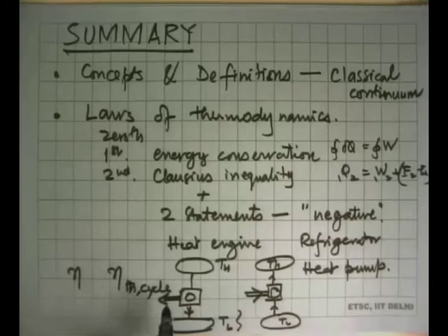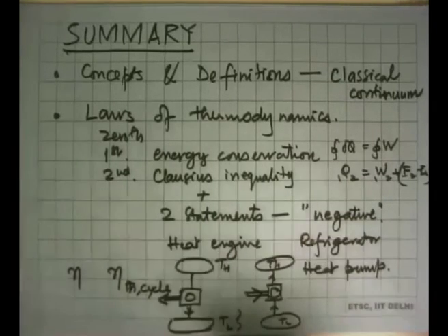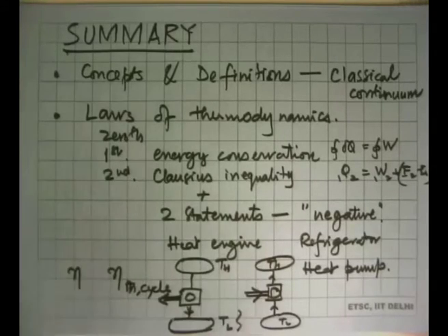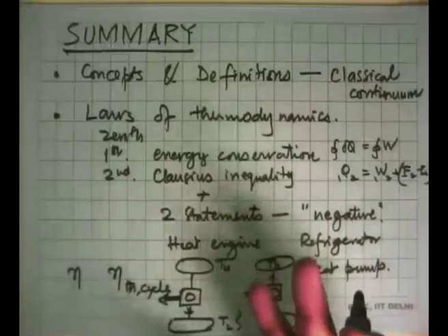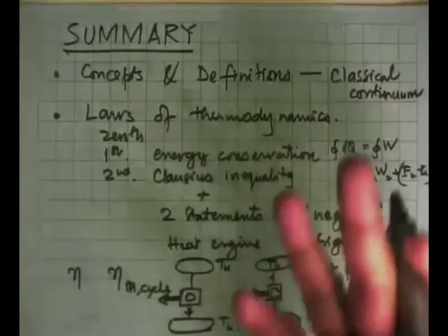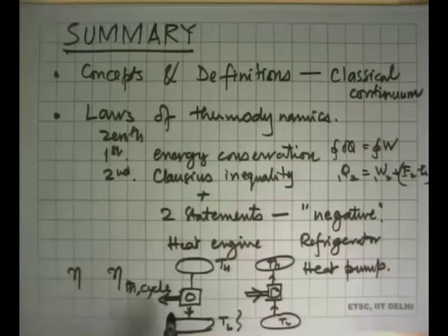You are consuming electricity. And if this train were to be running in a tunnel, then we are dumping energy into the tunnel air, which is the air going out, like you feel from an air conditioner outside, about 45, 50, 55 degrees Celsius. The Earth's temperature is about 23, 24 degrees Celsius, and if you keep dumping energy into the tunnel, the Earth surrounding that will be getting hotter and hotter slowly, but after 10 years, 20 years, 30 years, the Earth will become very warm, and then the only thing to do is to air condition the whole tunnel. So now you would be doing air conditioning of a tunnel to remove heat dumped by the air conditioning of the coach itself.